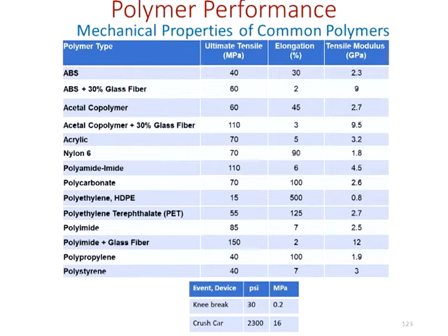I would expect that these are some trends that you want to memorize or learn in a course like this: the impact of adding fibers on the mechanical properties. And this chart shows you some very good comparisons, okay? And the real bottom line is that the ultimate tensile and the tensile modulus increase with the filler, but the elongation decreases.